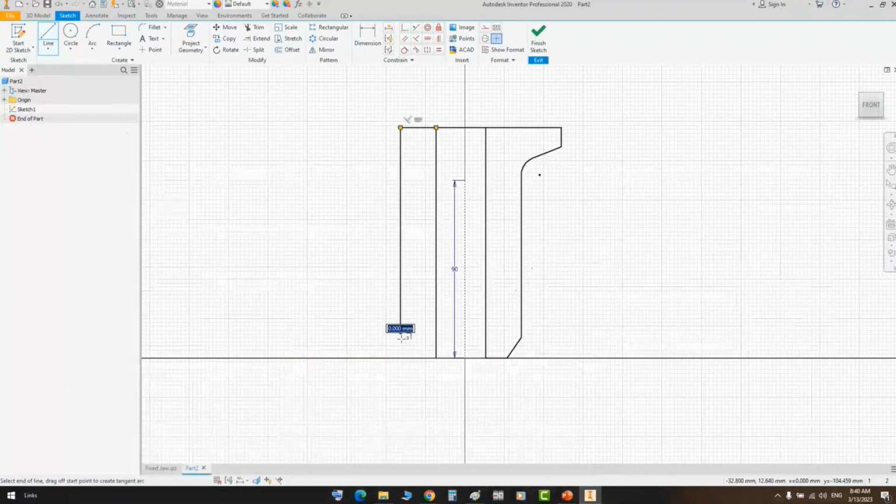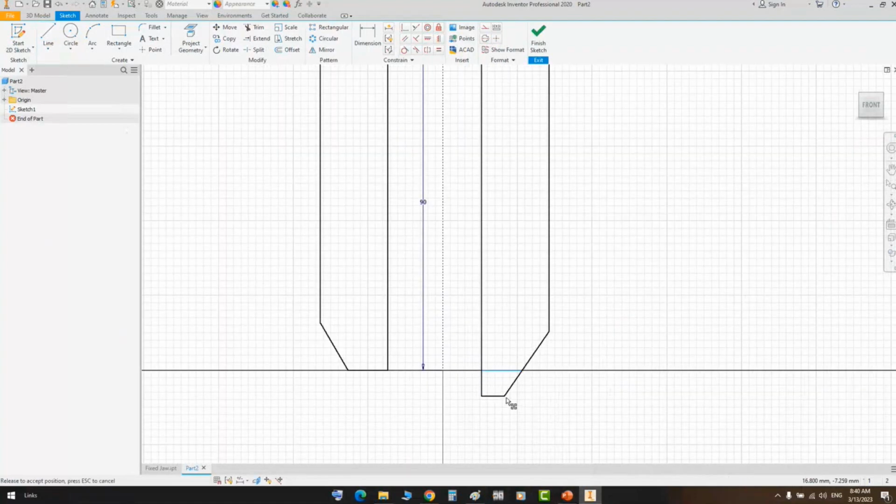It's straight with a chamfer at the end and this line. Now you can see that the end here is not fixed, and we need to align those with each other. So from collinear, we can make those lines collinear, and by using horizontal, we can make the level of this point the same as the level of that one.